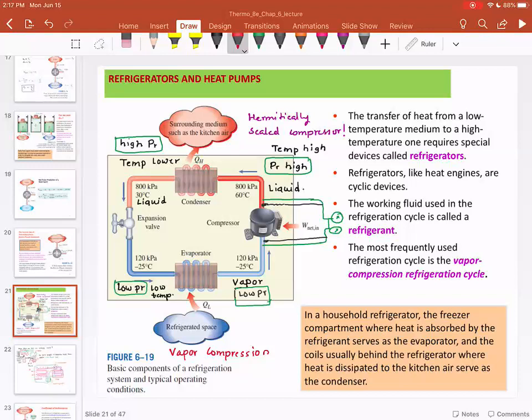As a matter of fact, jet engines are more efficient at elevated altitude because the air coming into the engine is pre-compressed by the high-speed air impinging on the jet engine compressors. That's why when the aircraft is flying, it's the most efficient.